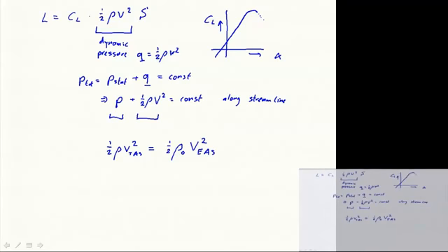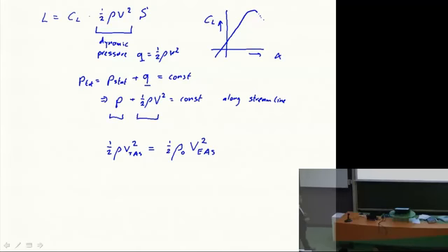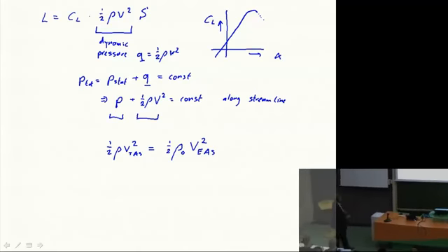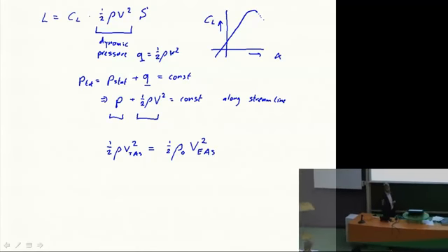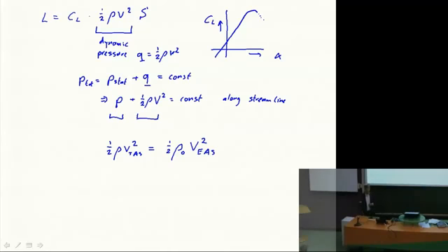So if we use a constant density, the atmospheric density at sea level, and we equate this to the real dynamic pressure, we can calculate the equivalent airspeed. And then there's something we can really imagine. An aircraft always flies the same with the same equivalent airspeed, because that indicates the amount of dynamic pressure that the airplane feels. So this also means if you go higher in thinner air, you have to fly faster to get the same flow, which makes sense.